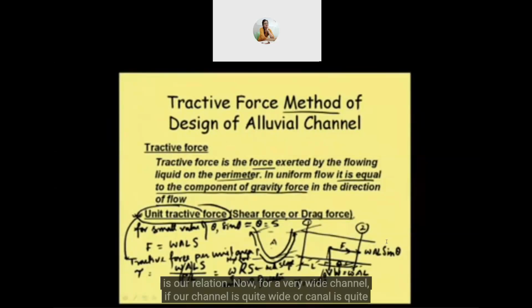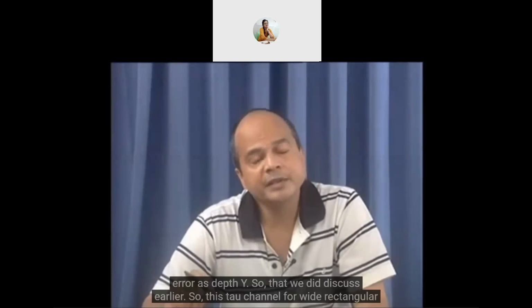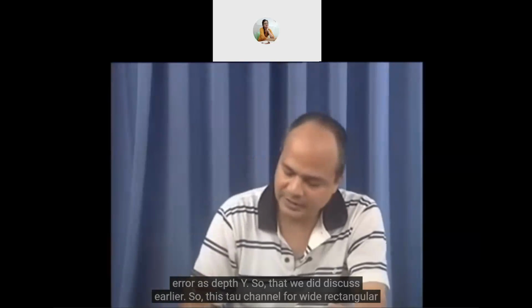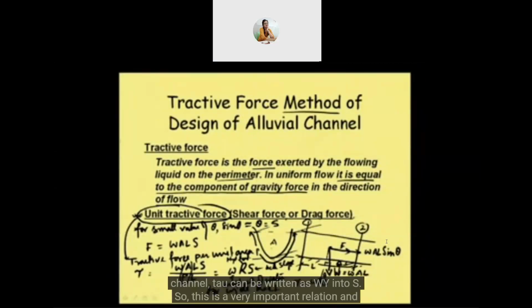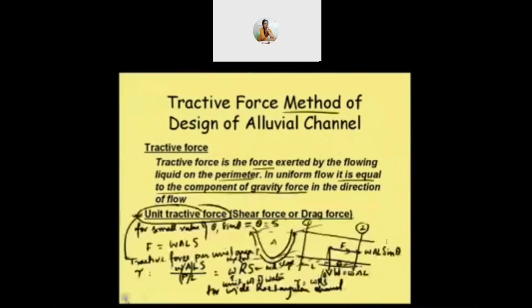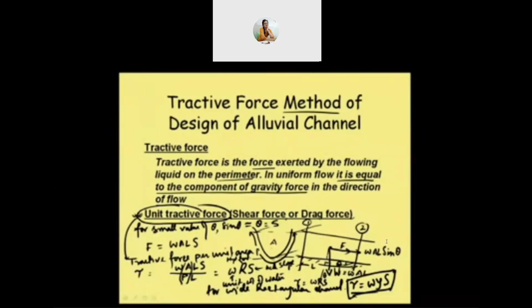And now for a very wide channel, if our canal is quite wide, then as we know, for a wide rectangular channel, this R can be represented with least error as depth Y. We did discuss that earlier. So tau for a wide rectangular channel can be written as WY into S. This is a very important relation, and is a basic equation for design of channel by tractive force method.